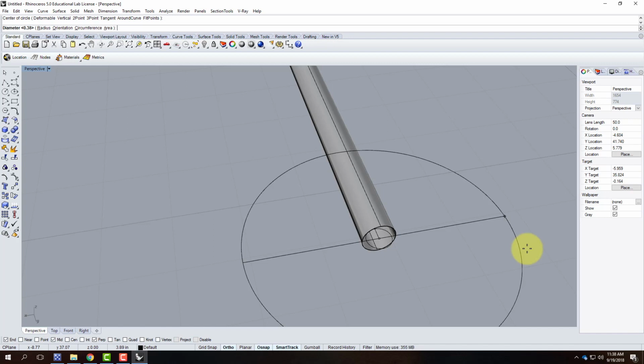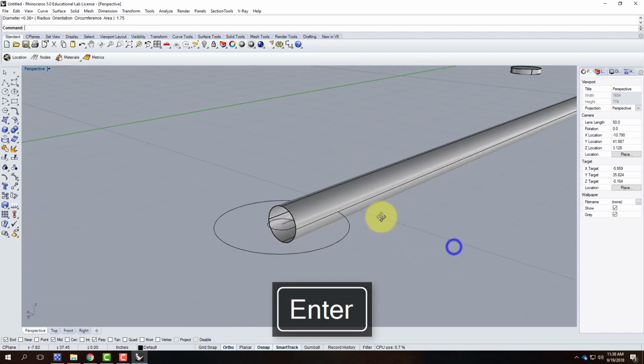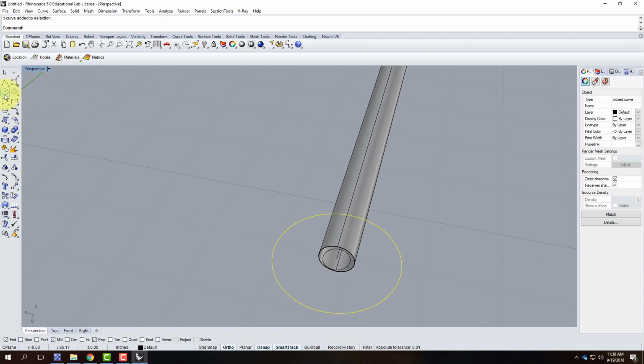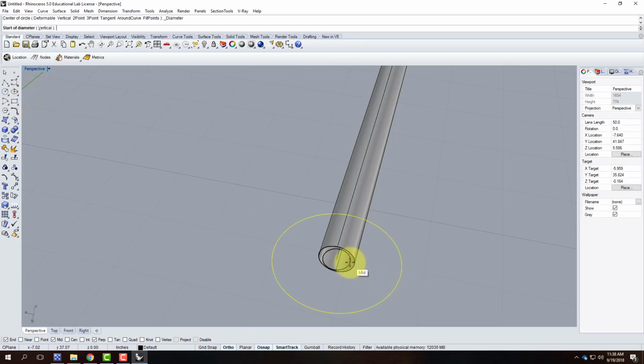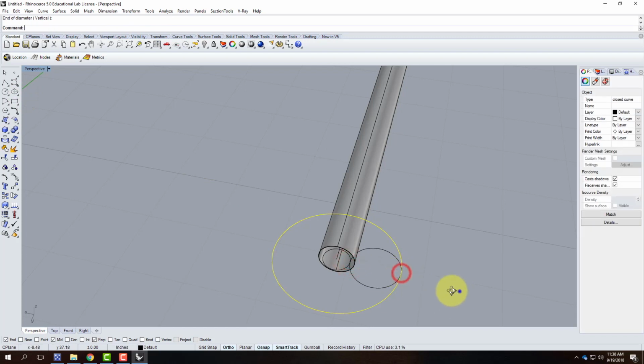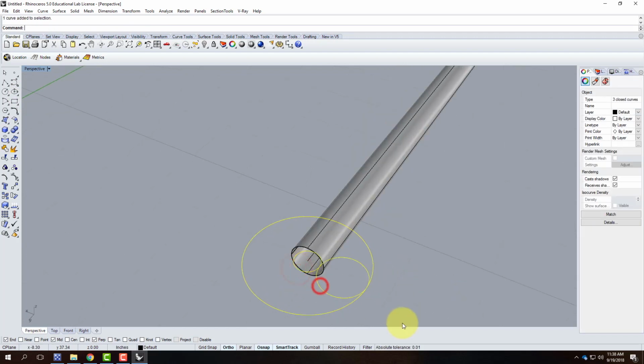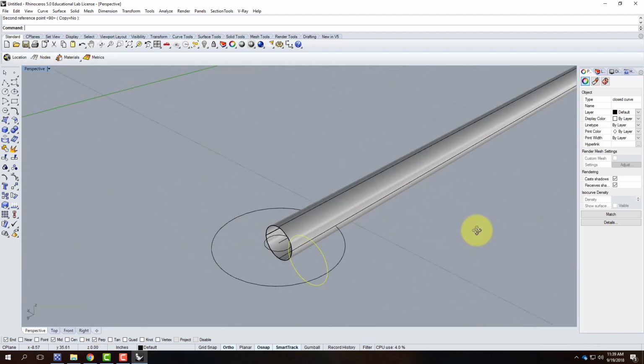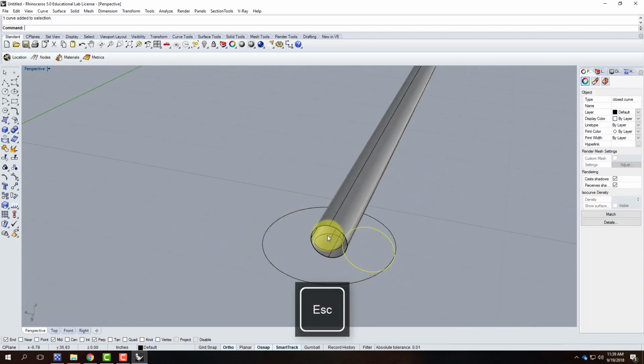Inch and 3/4. 1.75, and again, these are all in diameter. So there's my 1.75. So I have this inner one, and I have this outer one. I can do a circle, not a center and then a radius, but instead the diameter circle right here. And I can go from one side out to that side. So you see how I end up with these 3 circles? I'm going to do a rotate 3D on this circle so that it goes up like that. And I'm going to sweep this circle around one or the other of these curves.